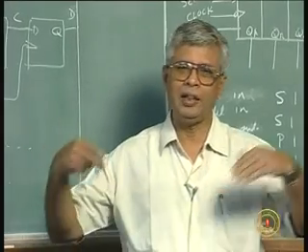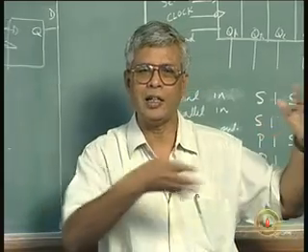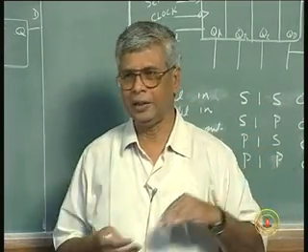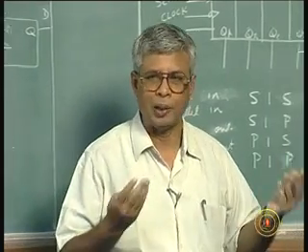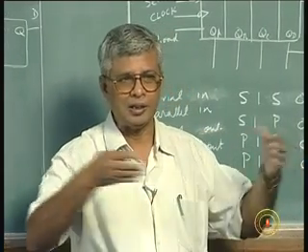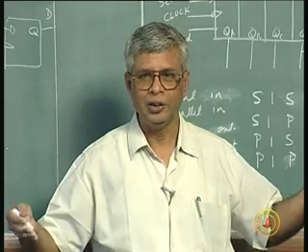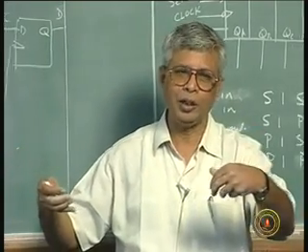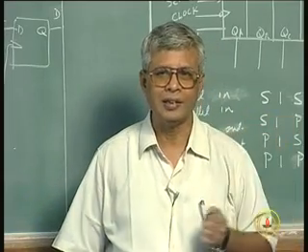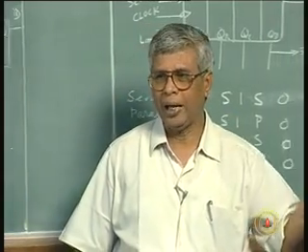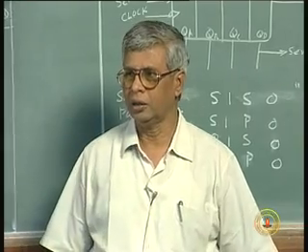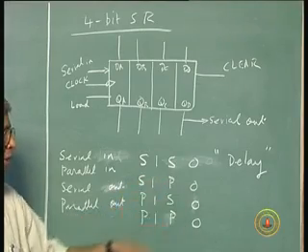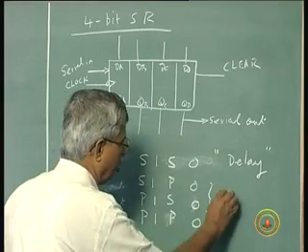Because the limitation is the telephone line, not the generation of data. I want to send a mail to you, my computer can give parallel output, your computer can also process parallel, but in between the medium is a serial telephone line. So, I have to convert my parallel data into serial mode data and send it to you, that is what my modem does, and your modem gets it back into parallel, is that right? So, these two things are covered, serial input parallel output, parallel input serial output. Examples are modems.